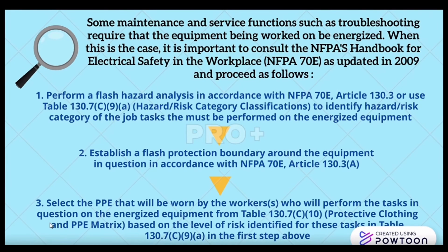Some maintenance and service functions, such as troubleshooting, require that the equipment being worked on be energized. When this is the case, it is important to consult the NFPA's Handbook for Electrical Safety in the Workplace, as updated in 2009, and proceed as follows.